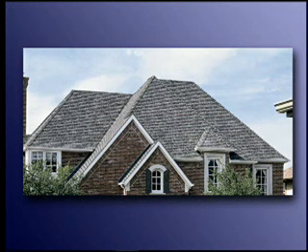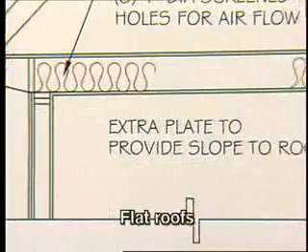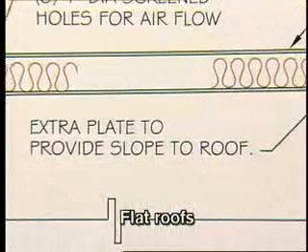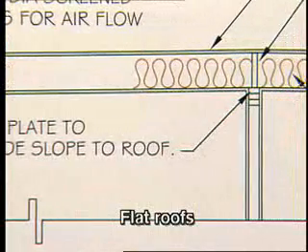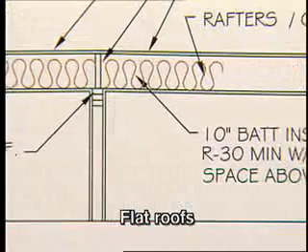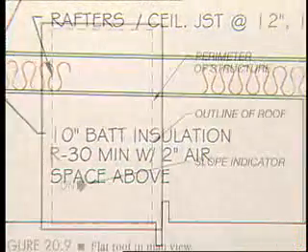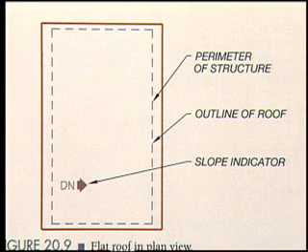There are two major categories of roof shapes: flat roofs and steep roofs. Flat roofs are not actually flat, but low-slope roofs with pitches lower than 3 in 12. Flat roofs cannot use the same finish materials as steeper roofs and require a monolithic barrier to water penetration. Flat roofs are more often used in commercial buildings, but have some appeal in residential construction in areas with little rain or snow.